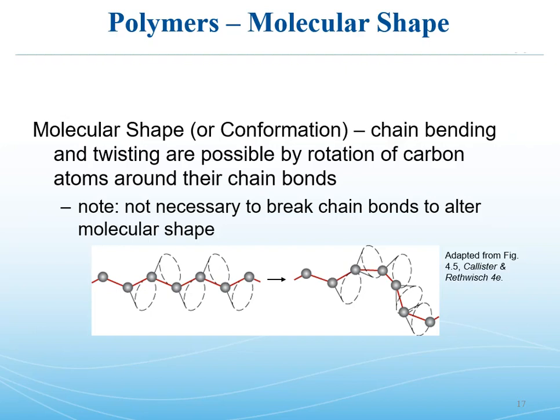and that's what leads to deformability and yield. And of course, as we go up in temperature, or if we leave more space between the molecules by, say, introducing a little molecule between as a plasticizer, we make it easier to rotate, easier for the chains to detangle and slip past one another.